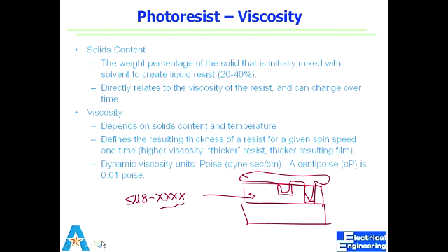Okay. Now think about it. Somebody can say, okay, if I have any resist, I can create any thickness if I want. All I need to change is the RPM and the time I spin it, right? Yes, we can, but we cannot always expose all of those thicknesses given the wavelengths that we have for this. Because yes, we can expose them, we do them for 2 hours, but then we can't get the features that we want. We can't get the critical dimension we want out of those, right?